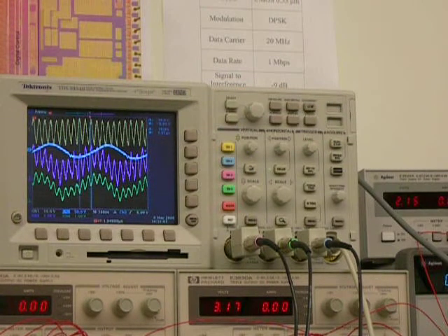The magnitude of the data signal and the power carrier interference oftentimes are in the same order of magnitude, and in a lot of cases, depending on coupling coefficient, depending on how much power the telemetry system is designed to transmit, the signal-to-noise ratio can range from one place to another. In this case, they're almost the same. Signal and noise are almost the same. So this creates a task for the DPSK demodulator to process it later.